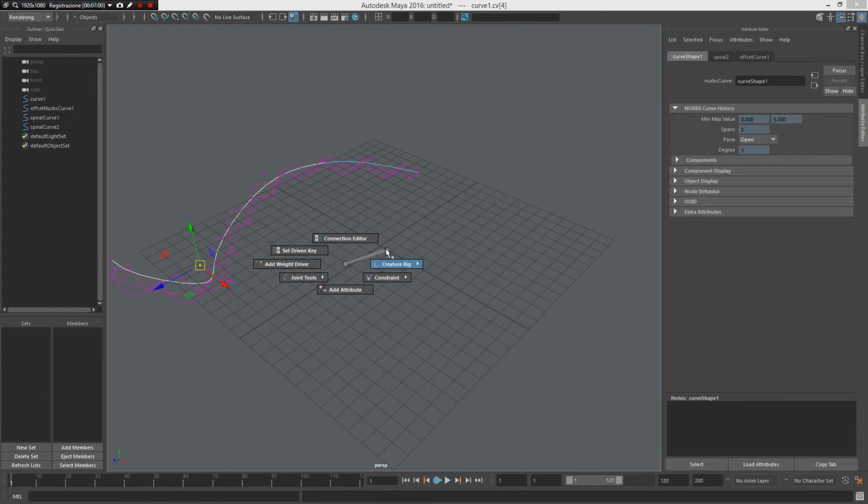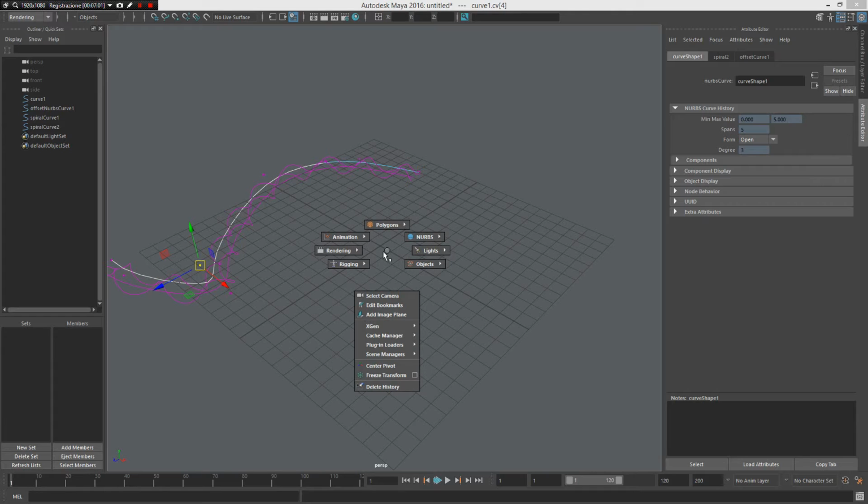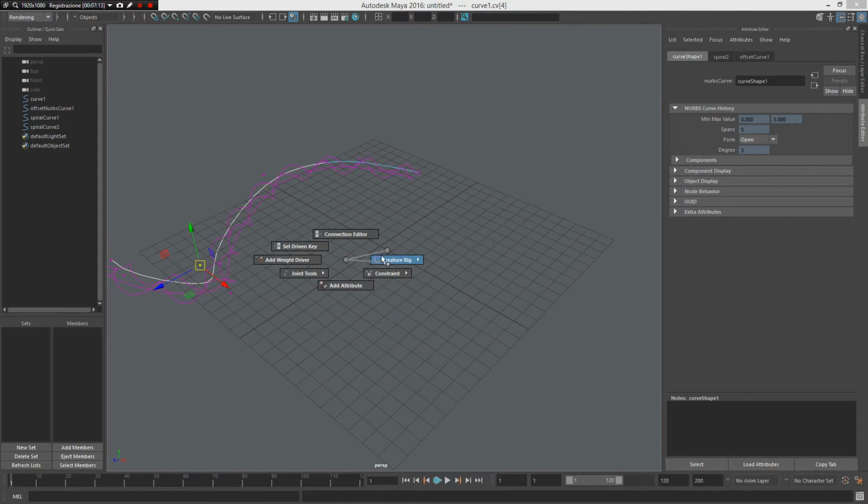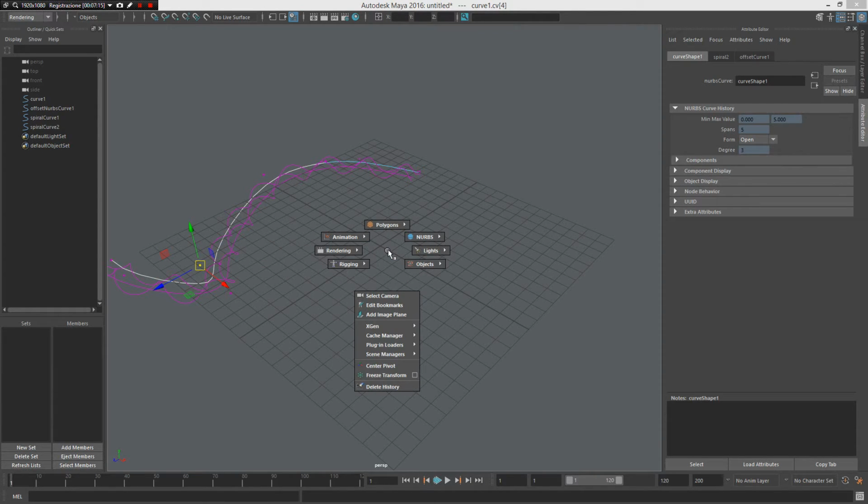You can't drive this feature by using the standard Marking menu editor from the Maya UI. You need to define it by entering the MEL code that drives the Marking menu. So it's a little bit tricky to set, but as you can see, you can add the icon to the group, and it makes it faster to remember and find the elements you need. I think it's a very great way to do that, and very useful too.